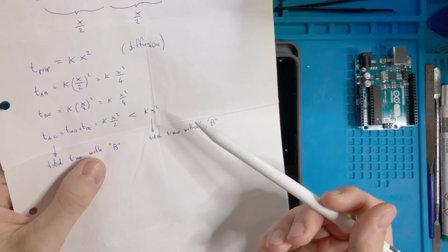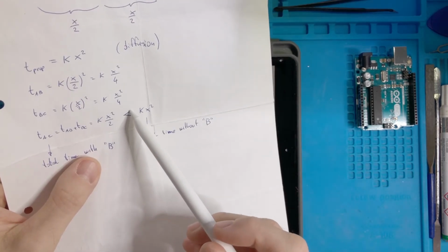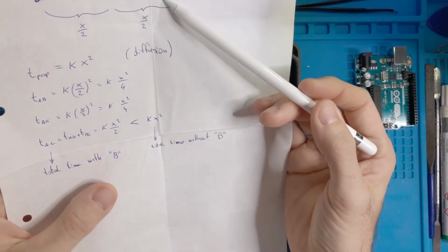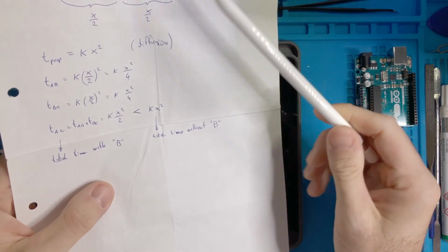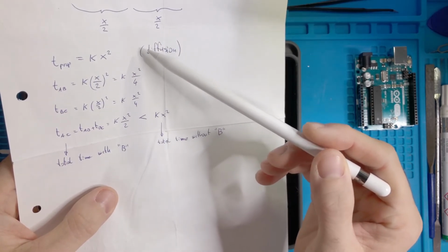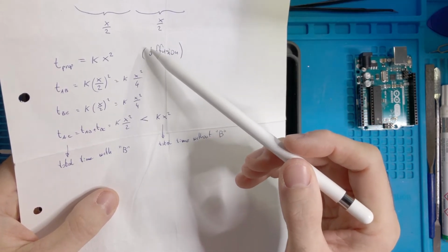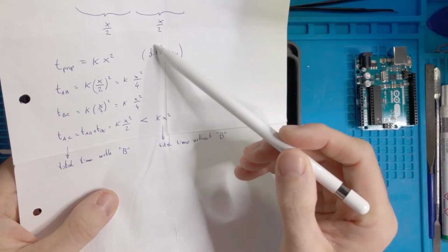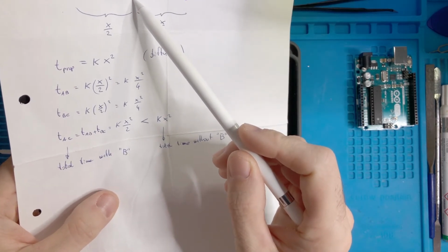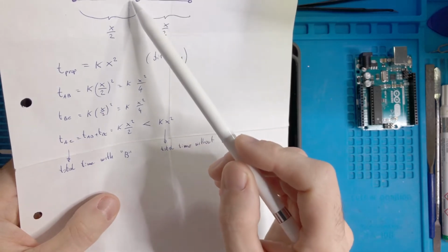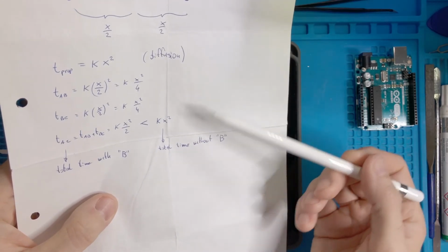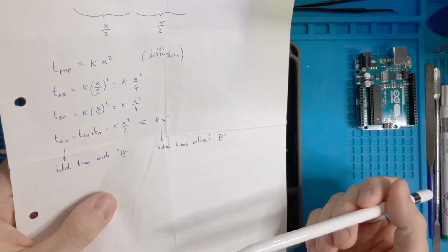which oddly, but it's like this, is smaller than the time for going directly from A to C. So the strange result is that when you have a propagation timing for which the law of propagation is according to a physics related to diffusion and not to waves, if you put an extra node in a path, so if you break the path in two, then the total timing of propagation is reduced, in this case by a factor of 1/2.